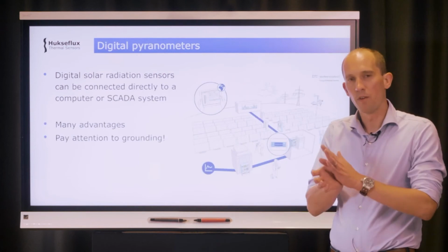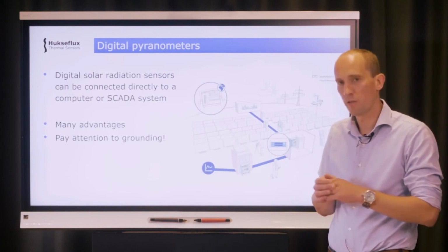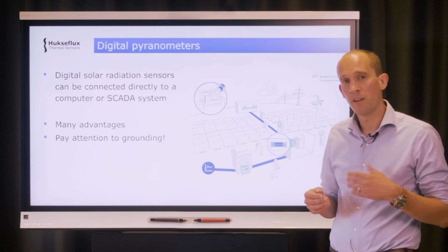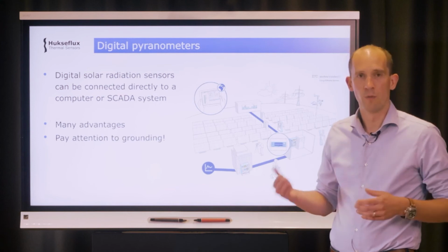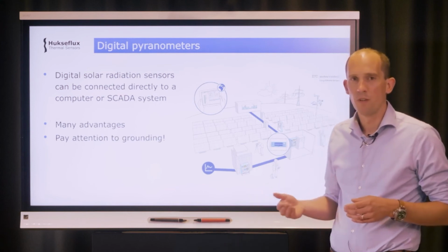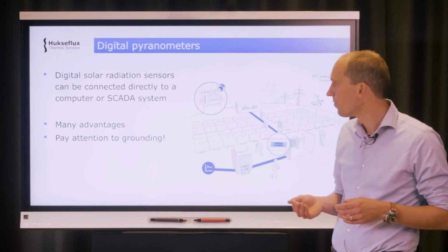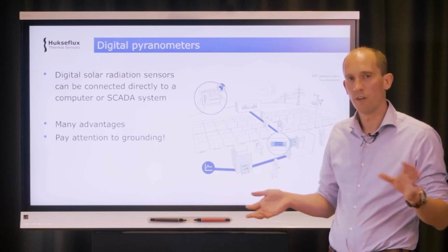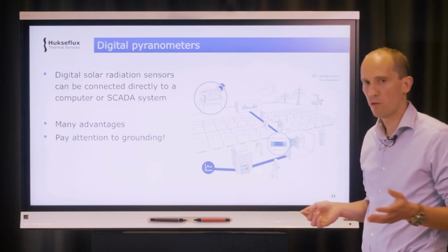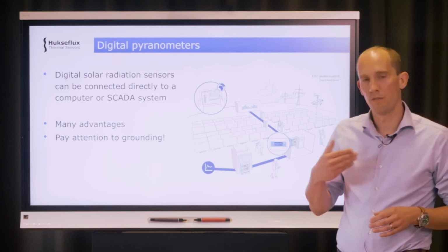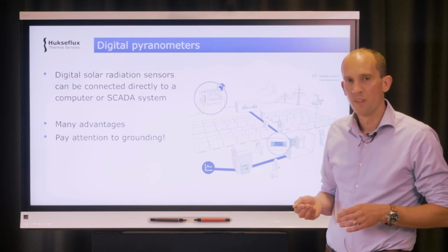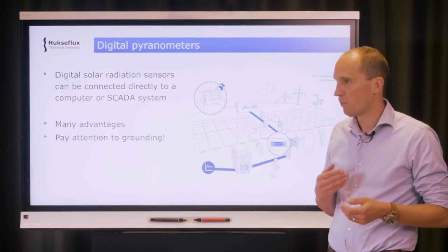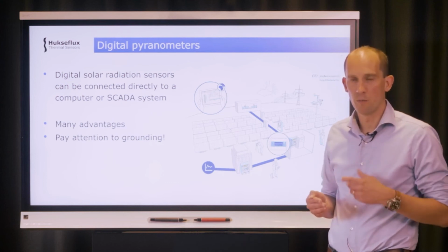There are also digital pyranometers on the market, which for the last few years have very quickly become the popular go-to pyranometer model. And they have the benefit that they are directly input into your computer or into your SCADA system, which is a data acquisition system. This allows people to build large networks and integrate them into their bigger power plant monitoring systems. There are a lot of advantages when using digital pyranometers. You get all kinds of information stored inside the instrument, you get temperature corrected data output, you get remote diagnostics.